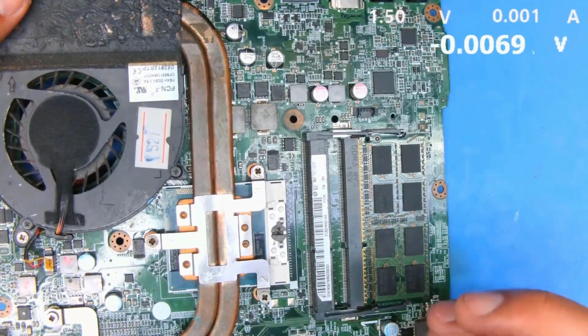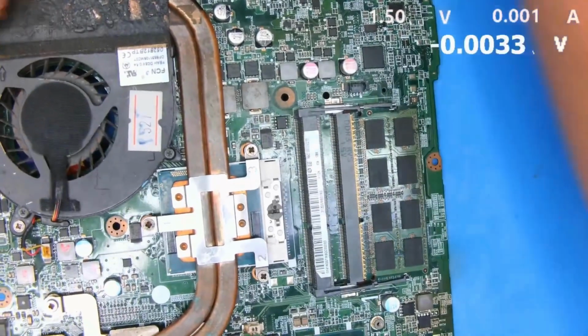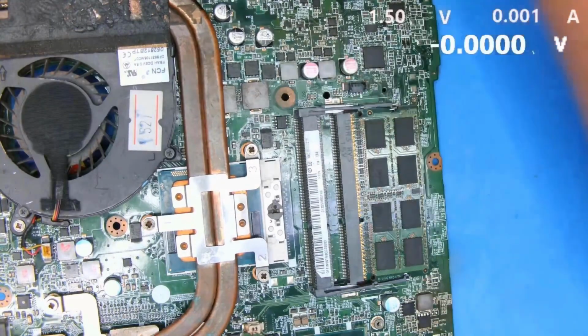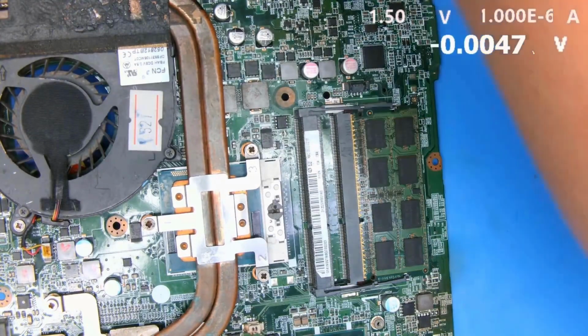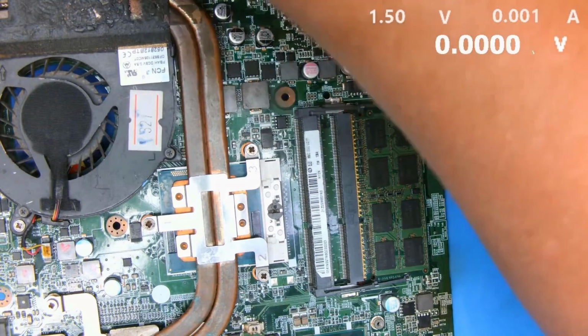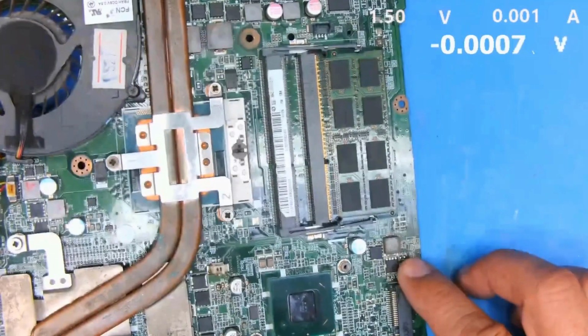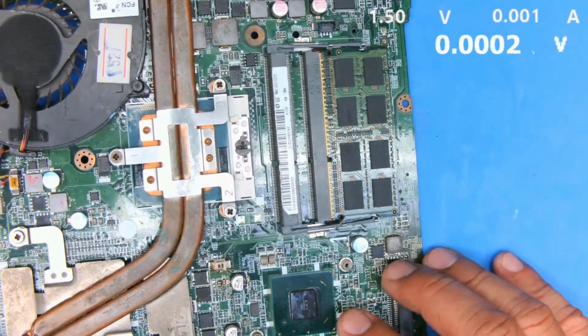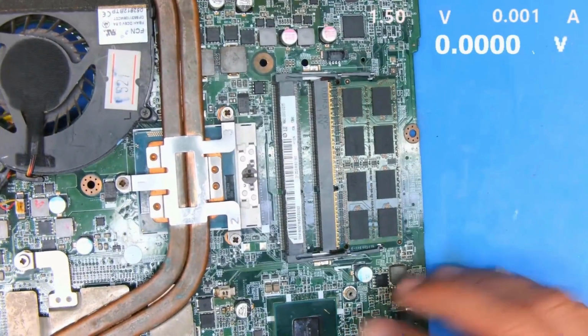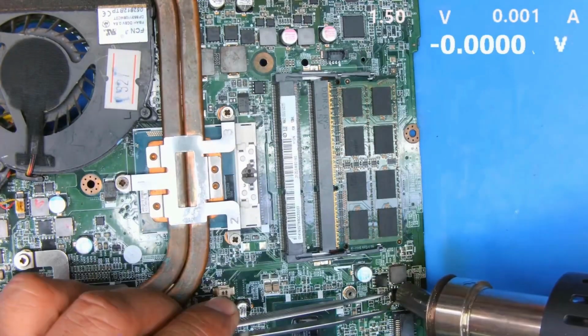Measuring with a multimeter is much easier. Right now, the meter already tells us that this is the faulty component. I will remove it now, and this time I won't supply power. You see, when I supplied power, I couldn't find the hot component. It didn't work. So I recommend that using a multimeter to measure is better. Just measure when it's cold. Use the diode mode. All right, now I'll remove the faulty MOSFET.